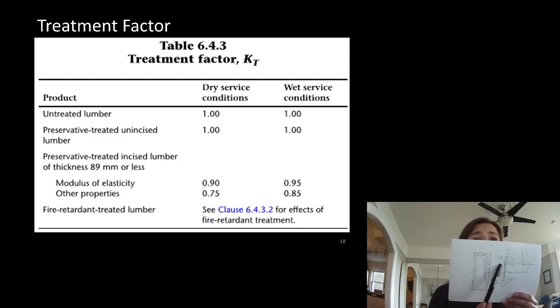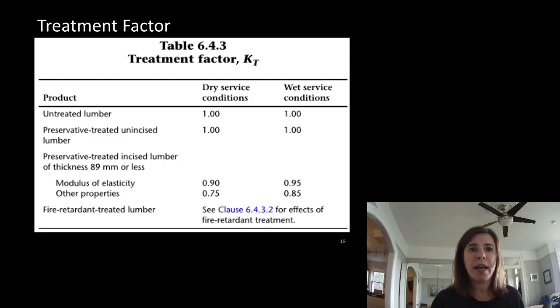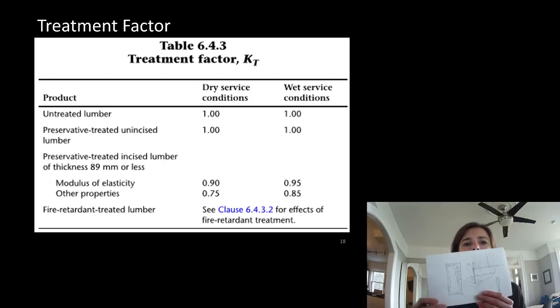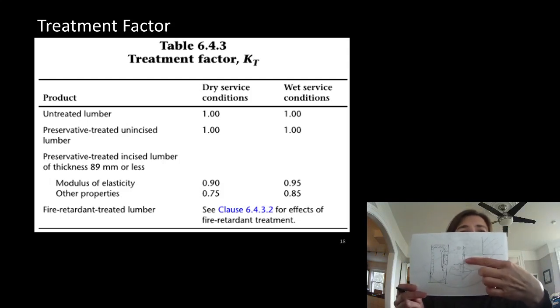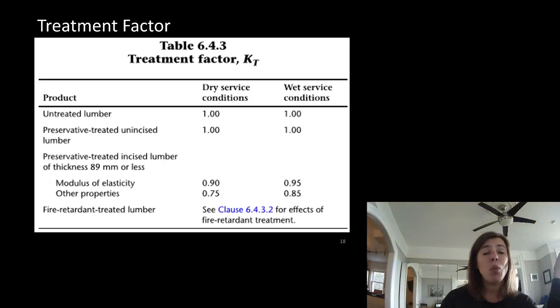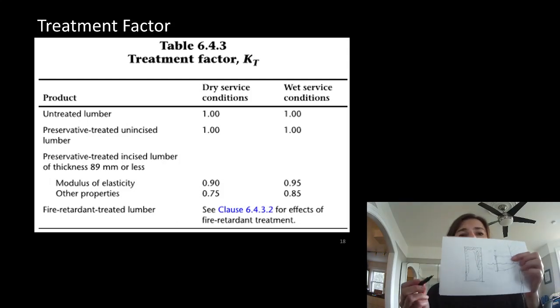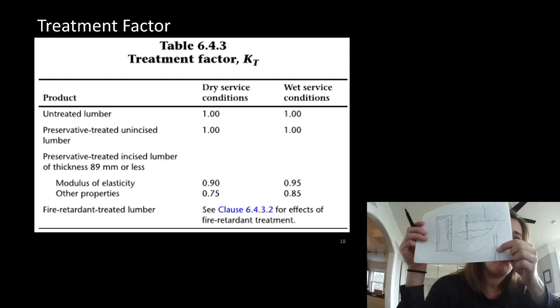But these posts right here were getting wet and getting dry. And in between us buying it and us getting to see it for the first time, the wharf was in the water at one corner. This is what happened. These logs that had been used to build that deck were wood that the first person who built it went into the woods in the back, cut down some trees, and just built their deck. They still had their bark on them. So what happened here is it actually rotted away, and there was nothing left.